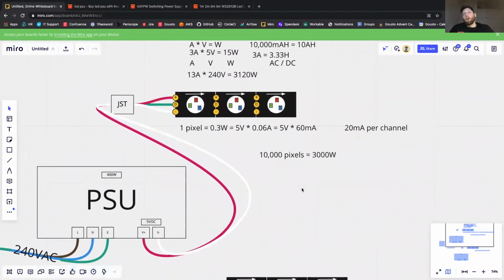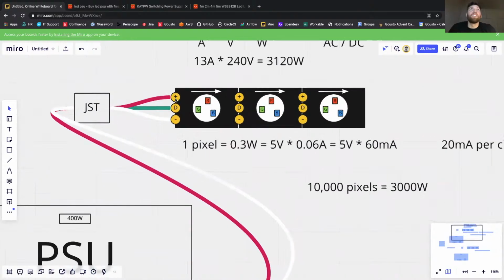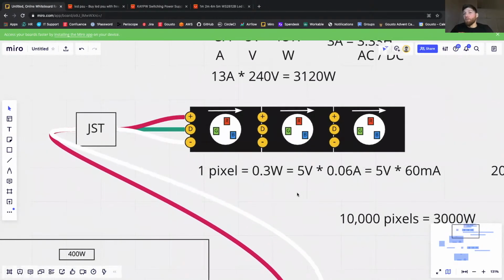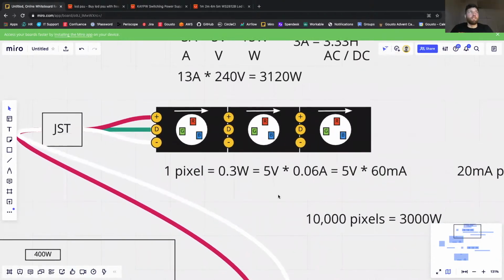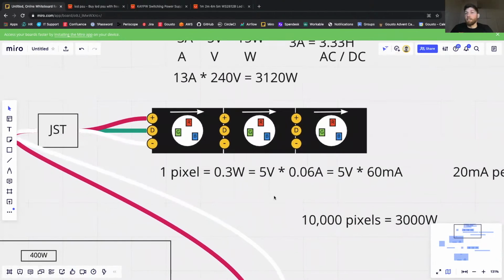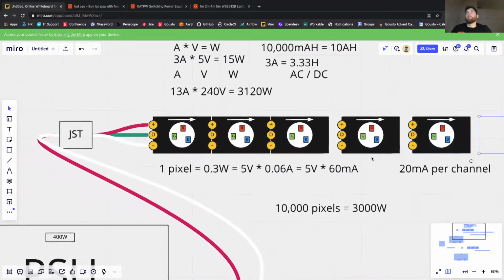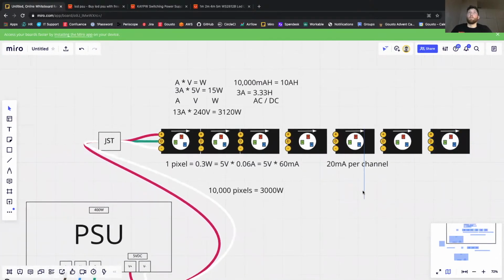Now, where does power injection come in? So it just so happens that these wires inside the printed circuit board also count as cables. And for that reason, they also have the capability to incur voltage drop themselves. So that means that even in a working, functioning LED system, over a long length of LEDs, you will incur voltage drop.